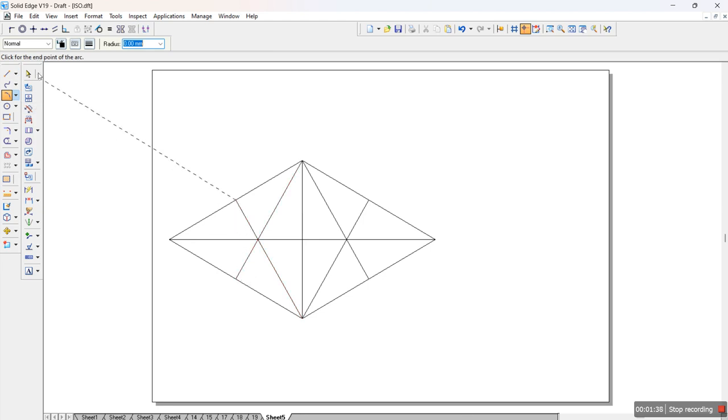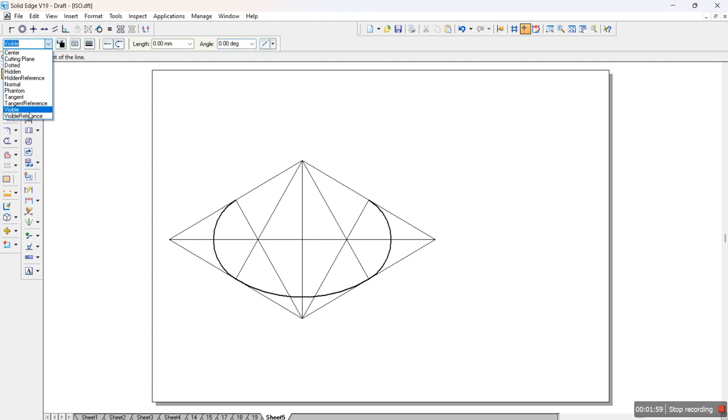from end to end. Make sure you change the line to visible. Don't forget to change the line as visible. Connect it out here from this point to this point. We'll connect it here. And similarly, from the end of this particular arc to the end of this particular arc, we place it here. Now we have the thickness of this slab as 30 mm. So I'll give the thickness of the slab from this particular direction, from this point 30 mm. I'll place it out here.